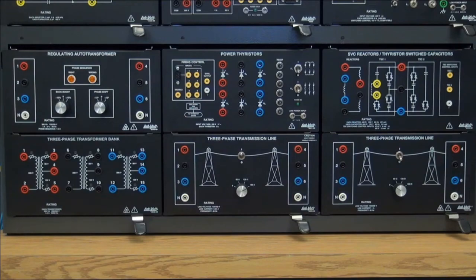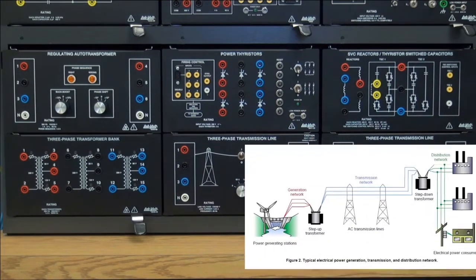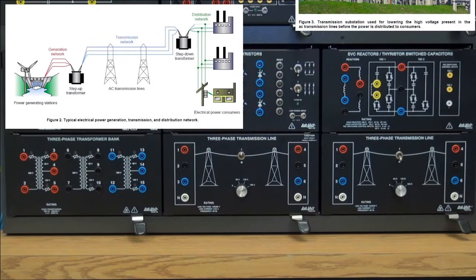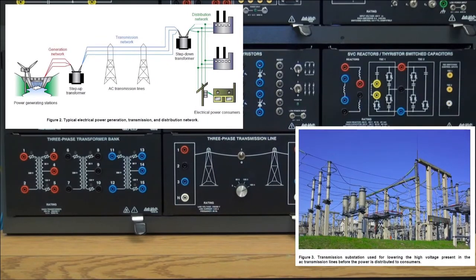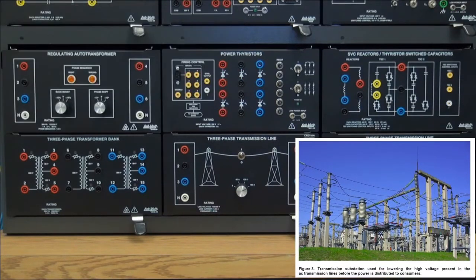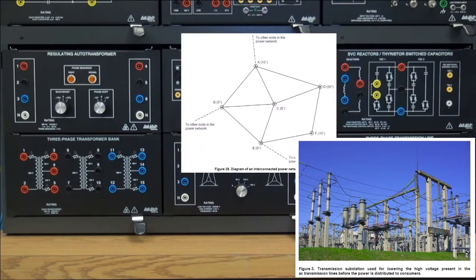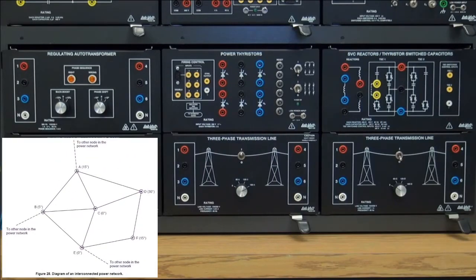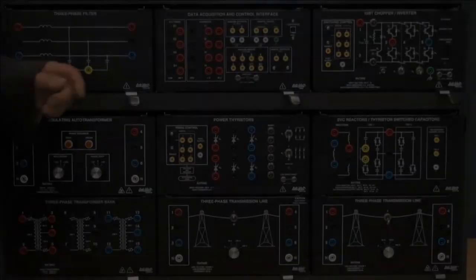Three-phase transformer configurations such as delta to delta, Y to Y, Y to delta, and delta to Y will then be studied. The students will then see AC transmission lines, learning voltage regulation characteristics, voltage compensation, power transmission capacity, voltage compensation in long AC transmission lines, and control of active and reactive power flow.